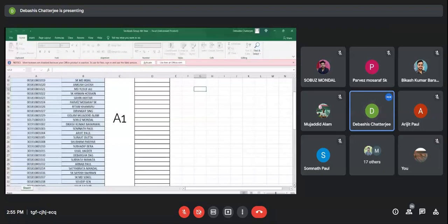3 phase, 415 volt, 50 hertz, 1500 watt. You make, I think, RPM, okay, let it be same. So we'll check the dimensions afterwards. 735 RPM, 0.85 power factor, 45 degree centigrade temperature rise. You design for minimum weight, right? So that your machine weight is minimum.